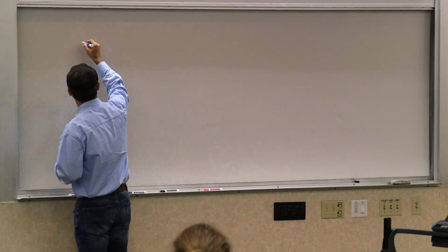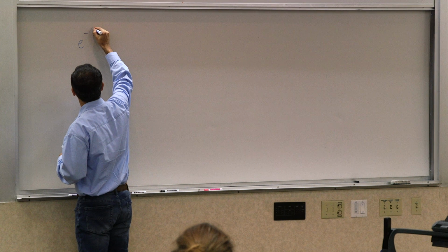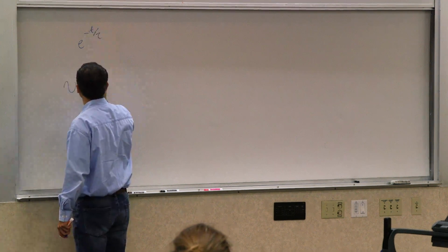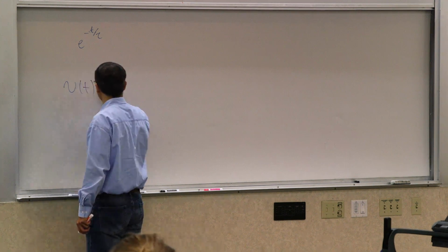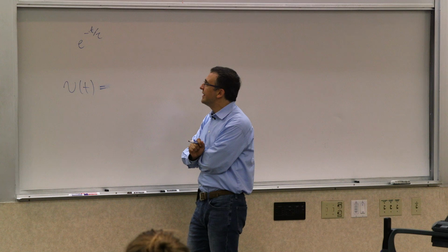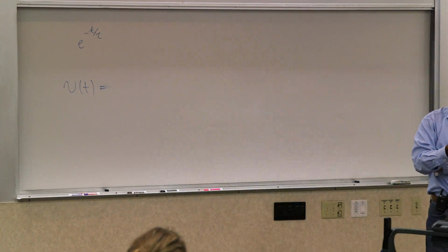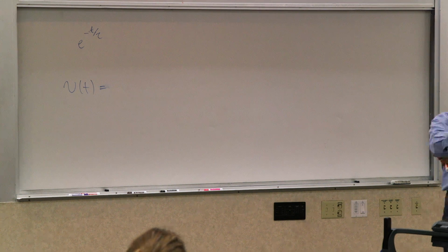So you have an exponential, e to the negative t over tau, with some time constant associated with it. We are trying to define the most general form for some v of t or i of t, some solution to this problem, when something happens at t equals 0. What if something doesn't happen at t equals 0, but at some other time? You can shift your time base to that point, assume that t equals 0, and take it from there.